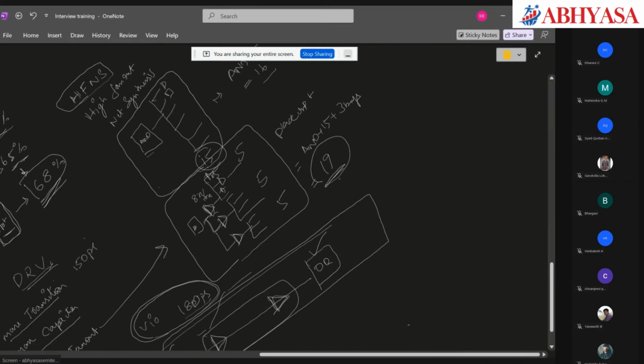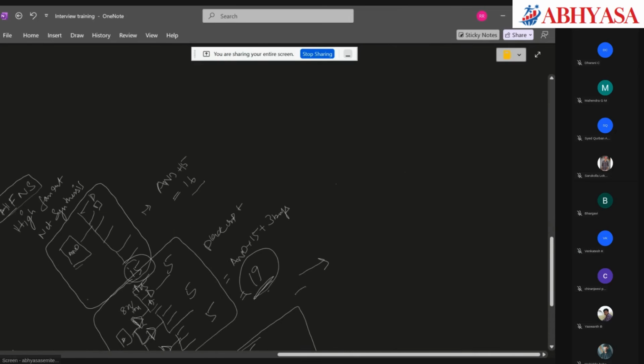Similarly, this is at place. Now we go on to CTS. At place stage, remember we have zero skew, so there are no clock cells. The clock is directly going to your flops. At CTS stage, I will have clock buffers getting added.